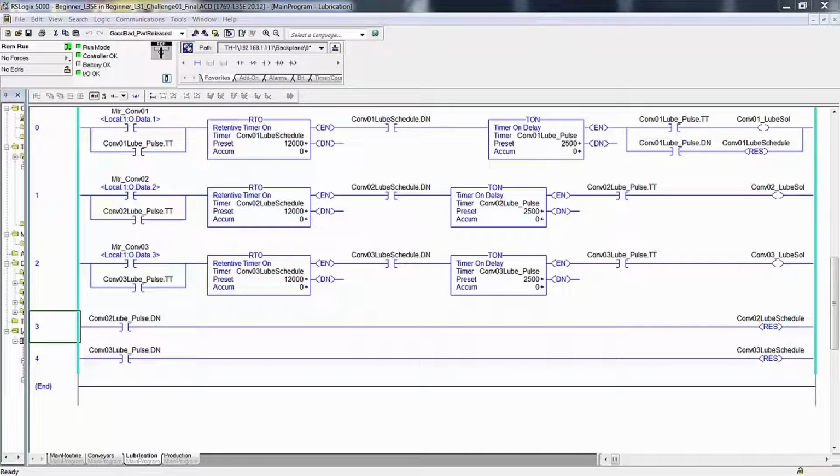That is a continuation of my previous statement about holding down the push button or leaving the switch on that represents the photo eye, and leave it on until you see the motor running, and then you can flip it back off, that is, release the push button. At this point, the counter for that conveyor will increment as having accepted it.